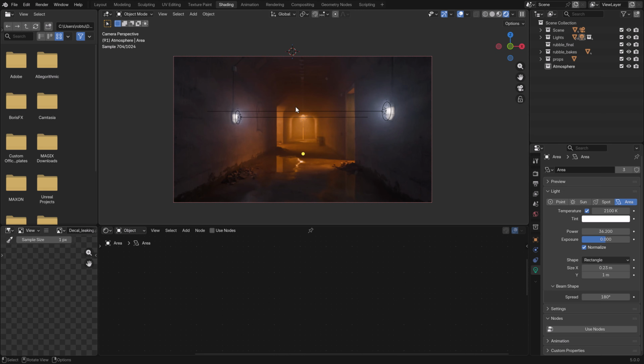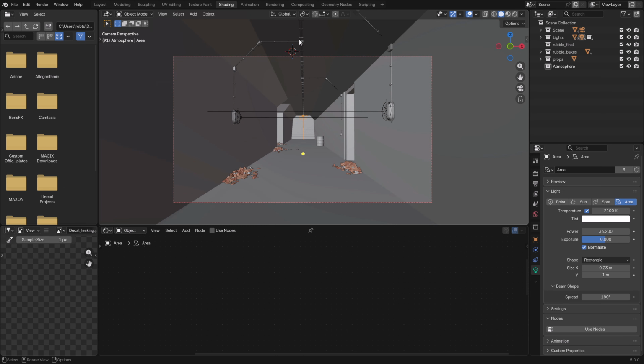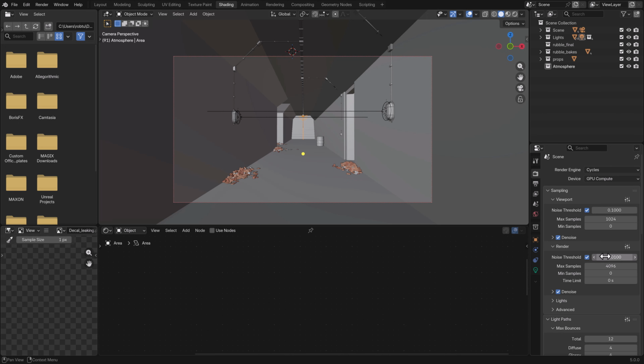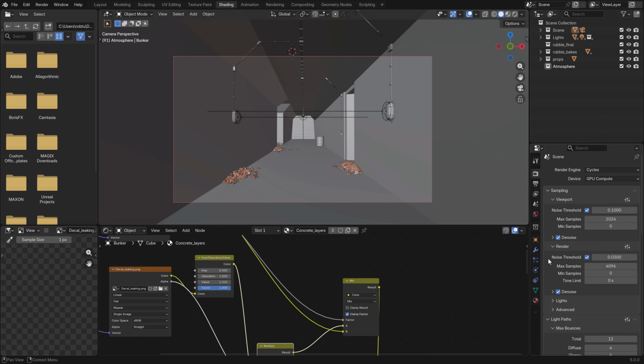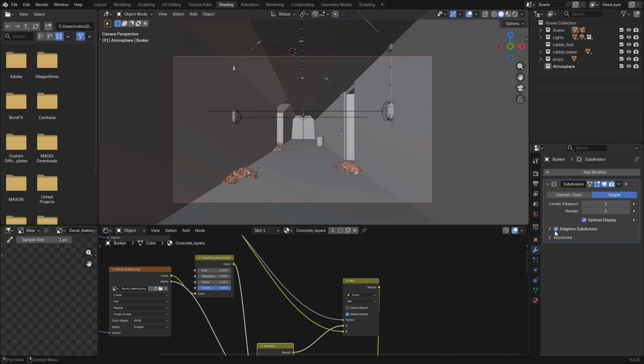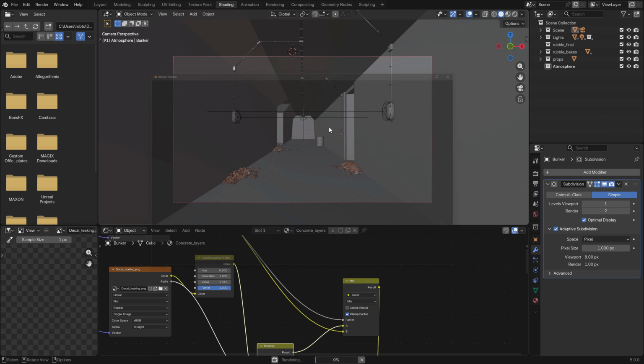One final thing I like to do is make a render. We go to the render settings. I like to lower this to 0.03 and increase this so it results in faster render times. I'm rendering this on a GPU. One other thing is you select the mesh, and you can increase this to 2 if 1 slows down your render. You will have a render impact and you will have less displacement. Okay, let's hit render. I will pause.